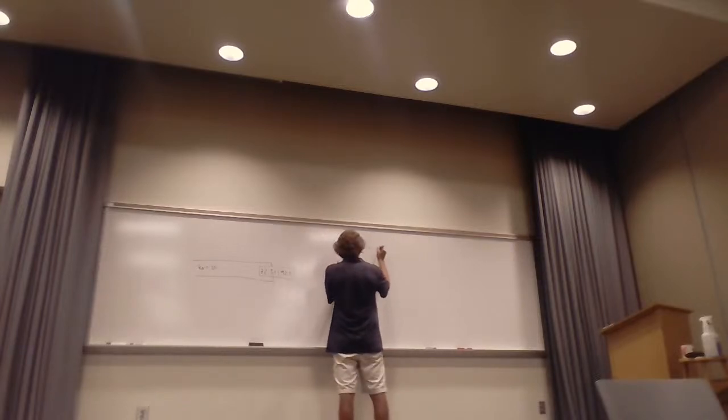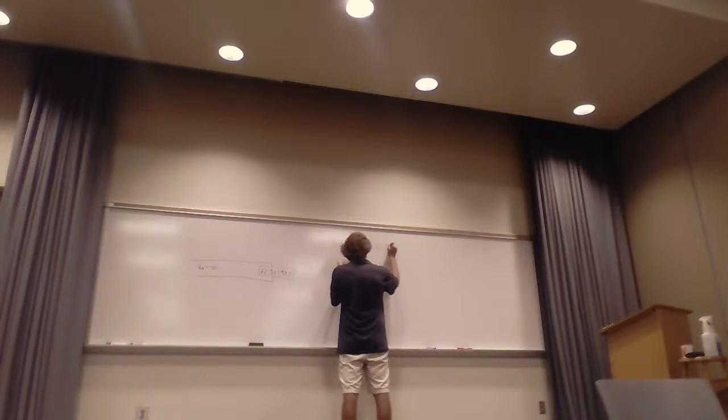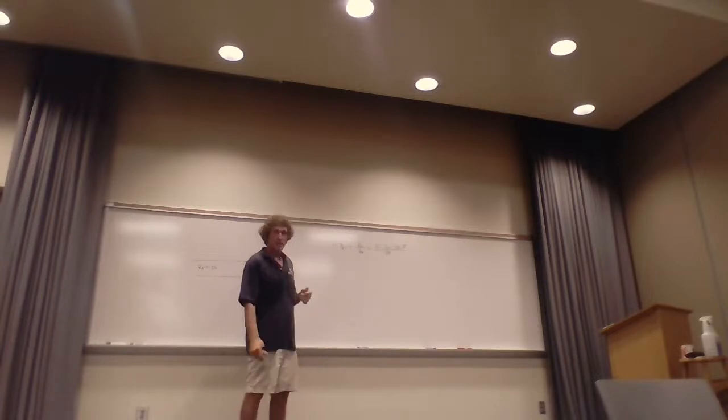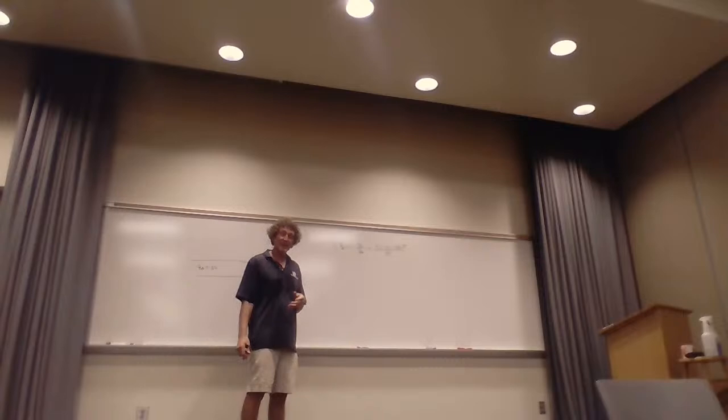So that's 72.3 plus J42.5 divided by 50, right? Y'all agree with that? I've got to take the normalized load impedance if you want to use a Smith chart solution. Y'all with me?